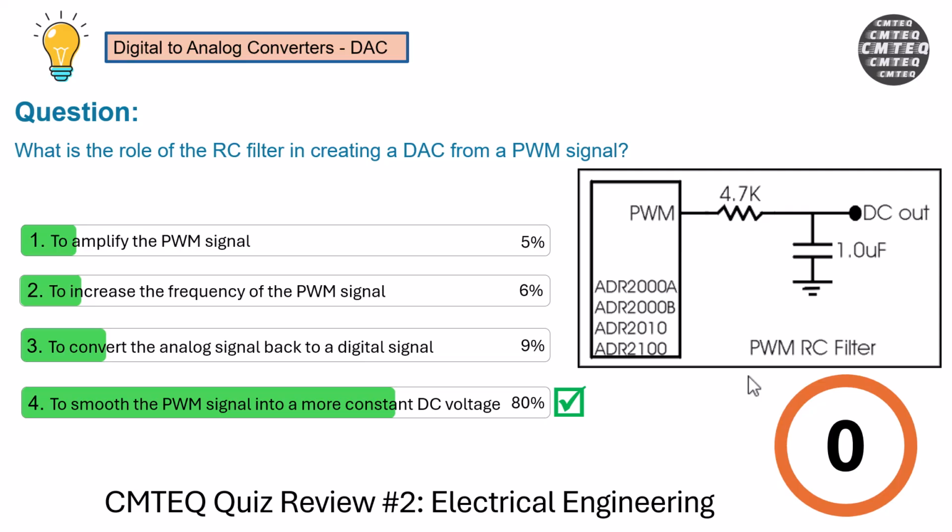Now, that system is much more complicated, right? Because you rely on precision resistance tolerance. So you can't use 20% or 10%. You need 5% or 1% precision resistors. And if the connections go wrong, then you've got problems, and the control of that system is pretty much hardware.